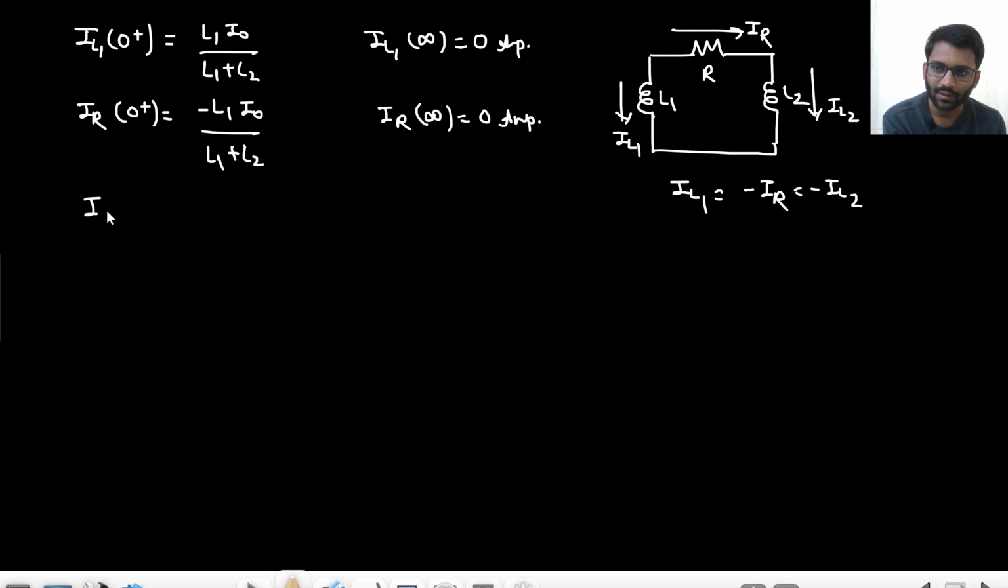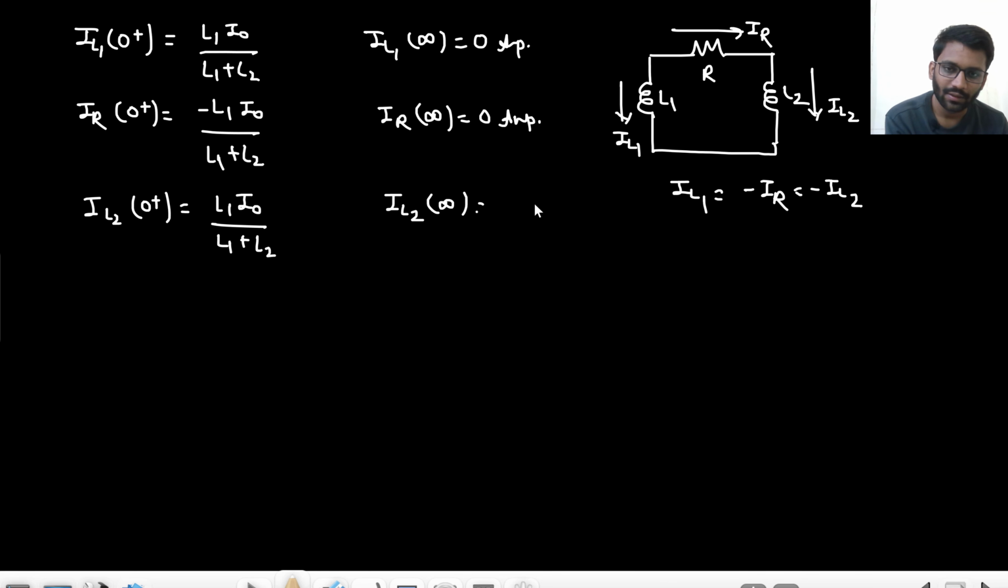What about IL2? IL2 at t equals 0 plus goes from 0 suddenly to some value, and then at infinity it becomes 0, right?